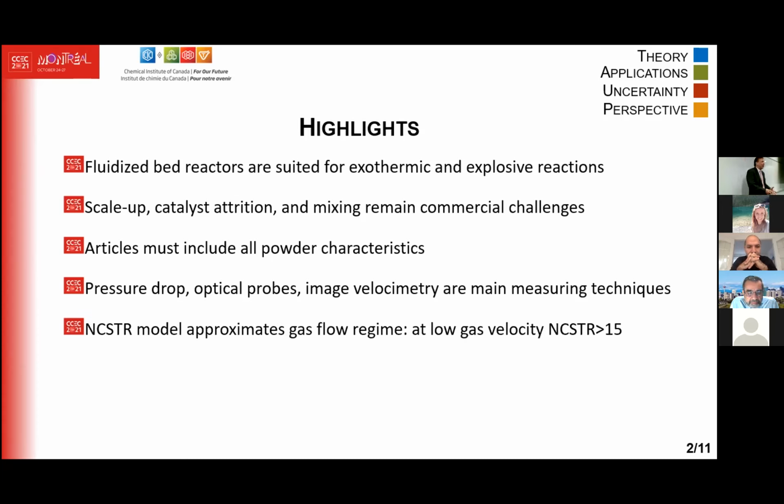Then what we want to look at is, again, the bad reputation. People talk about fluidized beds as backmixed. Well, that's not true. Solids are backmixed, and not necessarily perfectly backmixed. But when you're using the fluidized bed as a chemical reactor to understand kinetics, that's where the beauty is. Now you have to understand how simple models impact your kinetics, and so we'll talk about that.